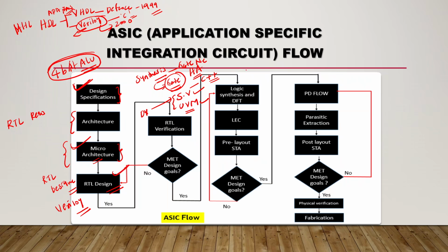After that comes logic synthesis. After the RTL designer has designed and the RTL verification engineer has verified, logic synthesis is converting your RTL design into a gate level netlist. A gate level netlist is nothing but hardware. So that is logic synthesis.